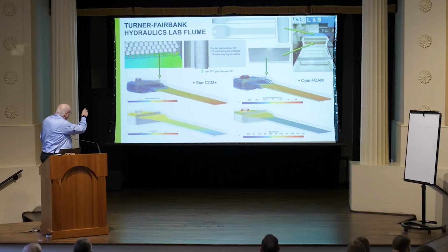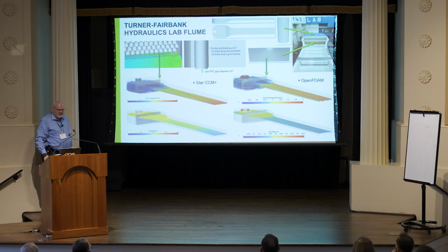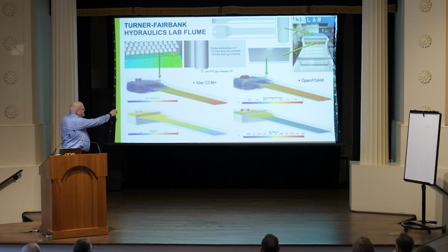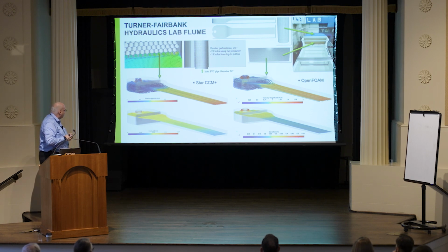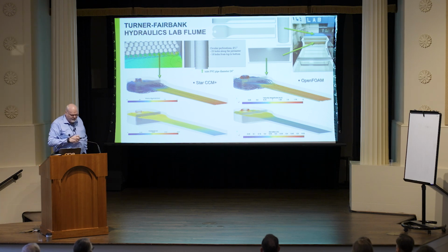And so on the left, on the bottom, you see the results that come out of the commercial software, Star CCM Plus, right? And then the same case, well, same geometry, but everything else was set up separately, right? Runs then OpenFOAM on the right. So you see the streamlines, the velocities, the water levels in the flume, things like that, right? So this is very typical for what we're doing.